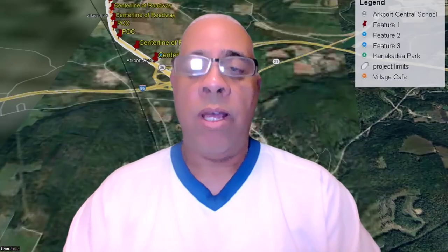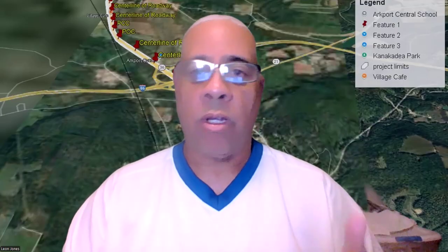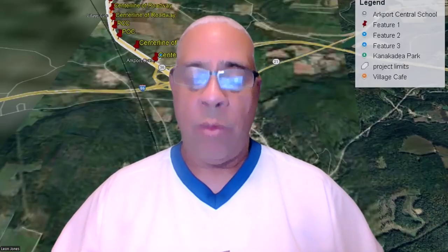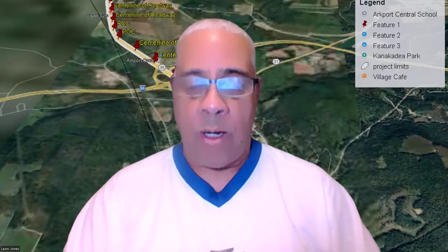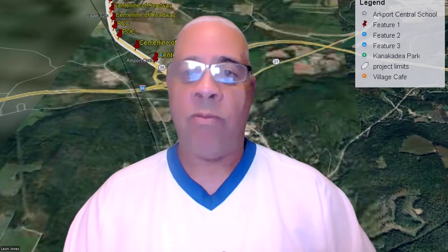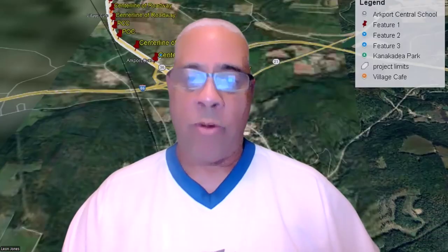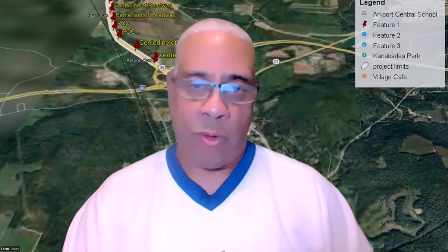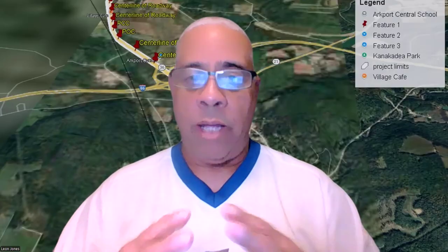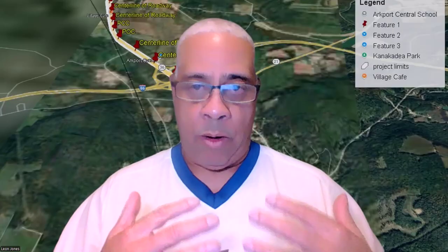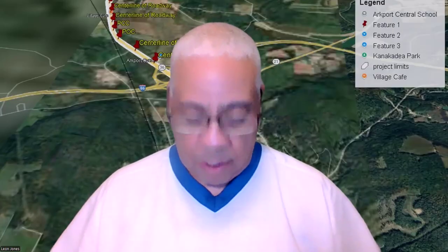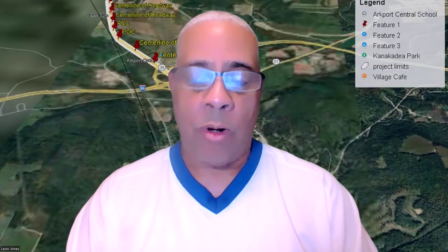And what I did is where you have all of those areas that have red pins, well, I took a segment of road and I actually marked all the control points, like the center line of road, your PCC, which is your point of compound curve, your point of reverse curve, that's the S curve, that's known as the PRC, and your point of curvature. And these are the points that I created so I could create an open network of control points.